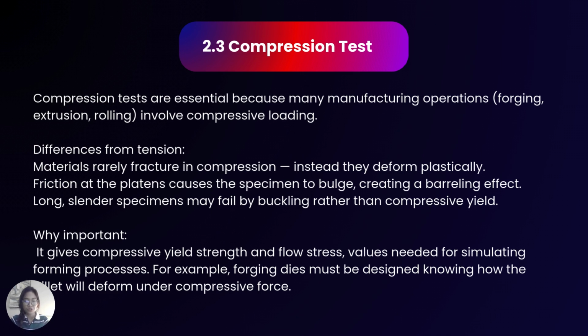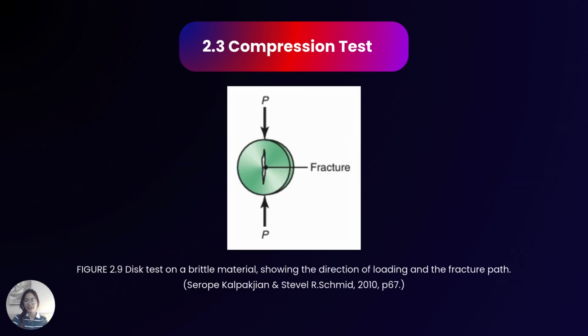Compression testing is critical for determining compressive yield strength and flow stress, values that are essential for simulating the forming process. This figure right here is an example that shows the direction of loading and the fracture path.